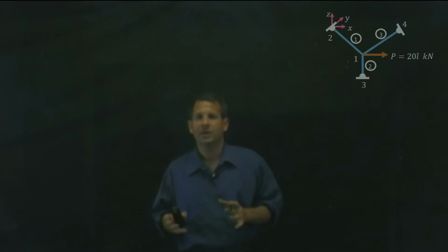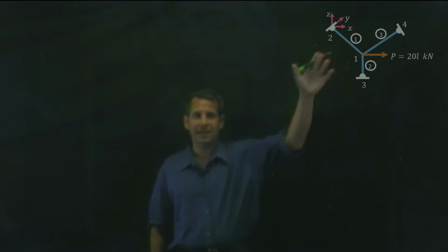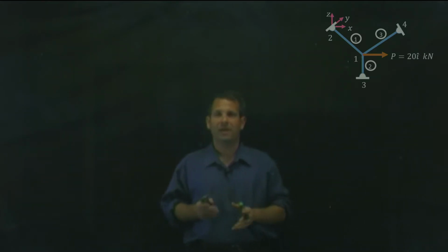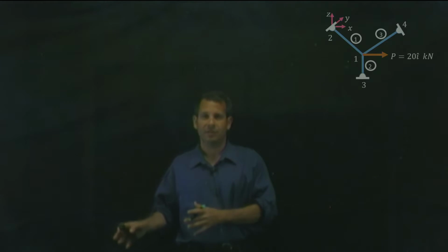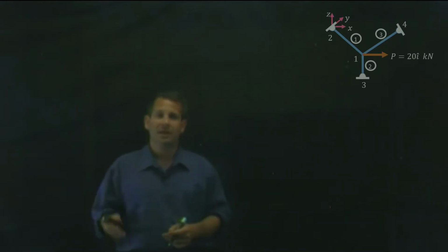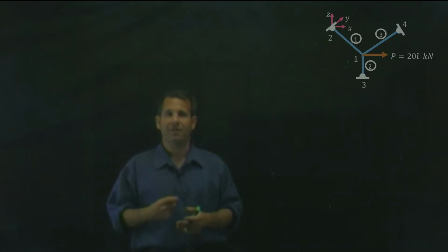We're continuing to solve our example 3D truss problem represented by this diagram here. In our last video, we completed step 3 of our solution process. We assembled the global stiffness matrix from the various local stiffness matrices found in previous videos. In this video, we'll continue on to the 4th step, applying boundary conditions. We'll also complete the 5th step, solving for the unknown displacements.